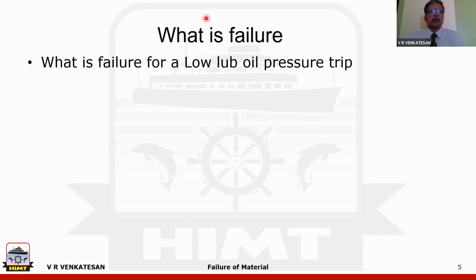If the vessel is in open sea with no traffic in deep water and the engine stops, it will not lead to any major consequence. But if this happens during maneuvering, or when you are close to land or in heavy traffic, definitely it can have a serious consequence. So the idea is that one type of failure, where normal lube oil pressure is there but the engine is stopped, is also a failure, but usually of a lesser consequence.